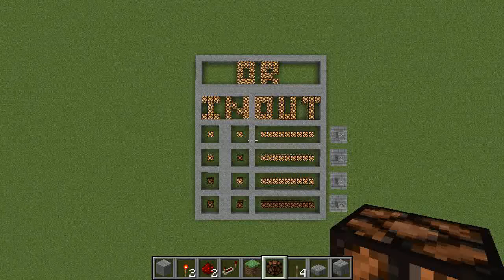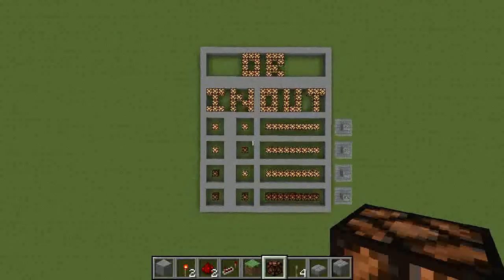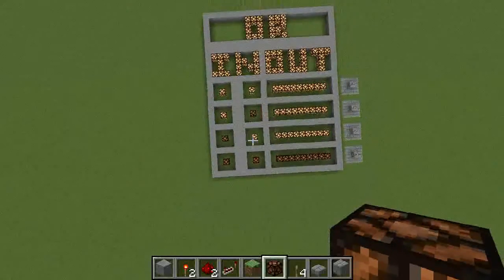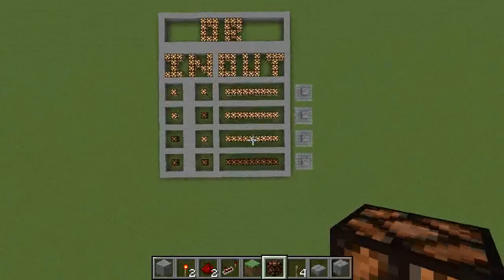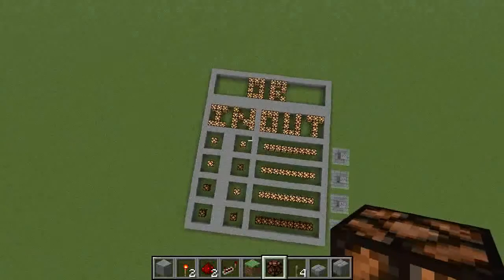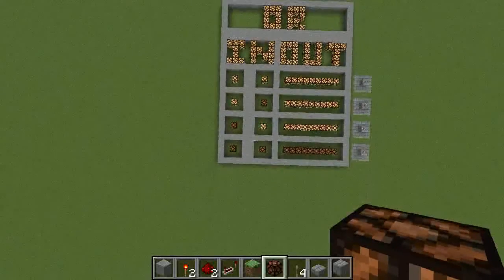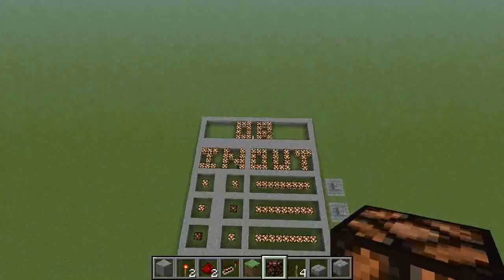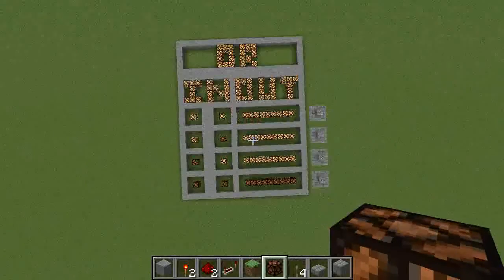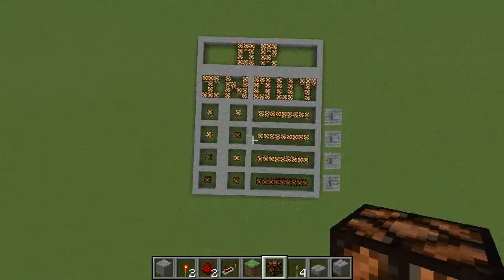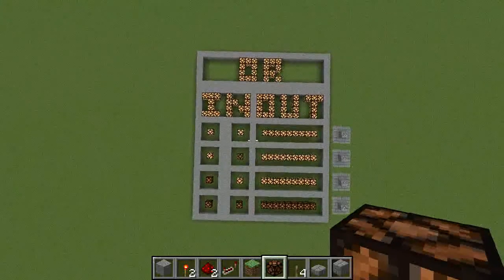So, to help lay it out for you so you can expect what each gate will behave like, I made what's called a truth table, which gives possible inputs, and we're working with just 2 inputs for now, and the output that happens for that specific gate. Each gate will have these same 4 inputs, which is on on, on off, off on, and off off. And then depending on the gate, the outputs for those inputs will be different. That's what makes each gate different. That's the good part about the gates. They can do all sorts of different combinations.